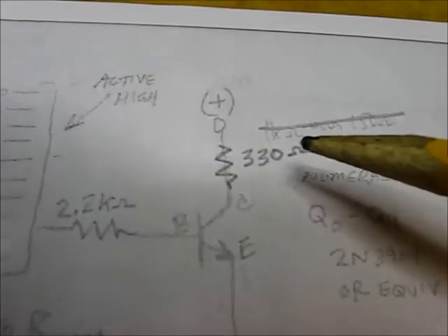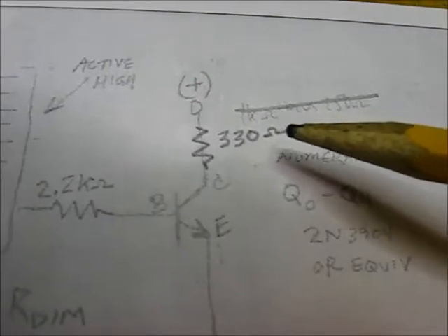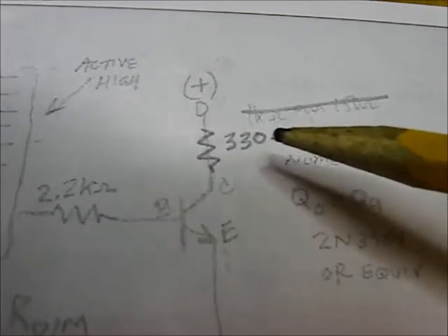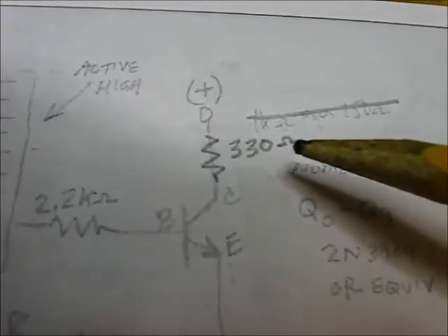Keep that in mind. Up here I had initially in the design a variable pot with the idea of dimming the display. Well, that didn't really work out because the base current through the transistor was still enough to keep the LEDs on. So I couldn't really dim enough, so it wasn't really worthwhile putting that in there. Although extra current limiting I found after operation of the circuit is needed. So I had already installed these 220s down here.